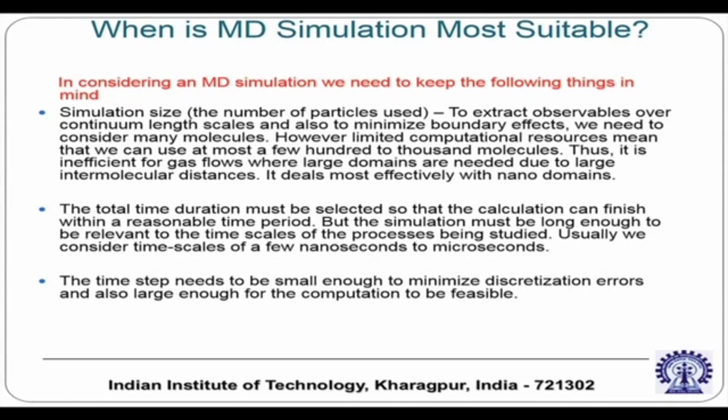When is molecular dynamics simulation most suitable? In considering MD simulation, we need to keep the following things in mind. Simulation size: by molecular dynamics we mean it is not a grid size, it is the number of particles that we think of. To extract observables over continuum length scales and also to minimize the boundary effects, we need to consider many molecules. However, limited computational resources mean that we can use at most a few hundred to 1000 molecules, in normal computational platforms.